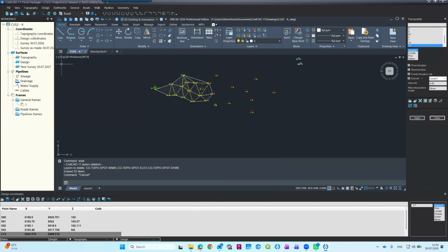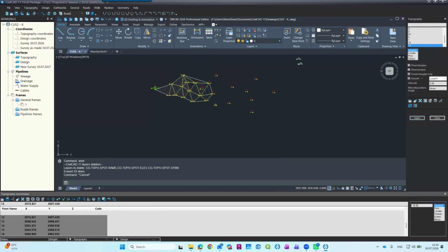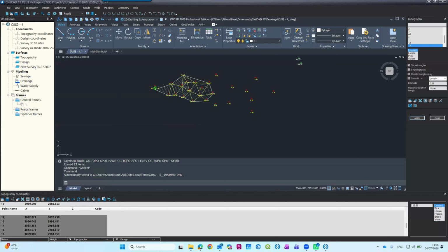If I want to take a group, let me go back again to the topography and select a group from here till here with Shift. But I can also do it geographically. How do I do it? I'm going here to locate, and the software asks me, what do you want to locate? Polygon in, polygon out, or a single point? What are you trying to work on? So I said, I want to work on a group, a polygon of points. Polygon in, I.